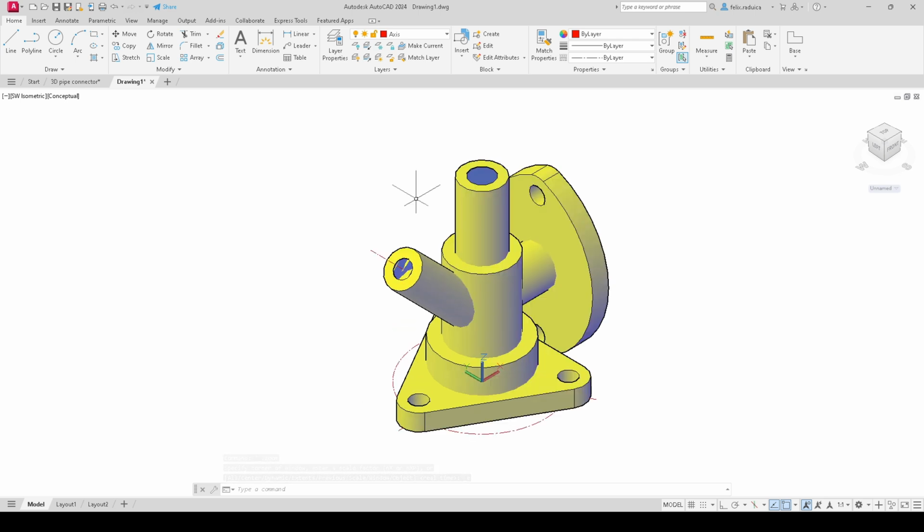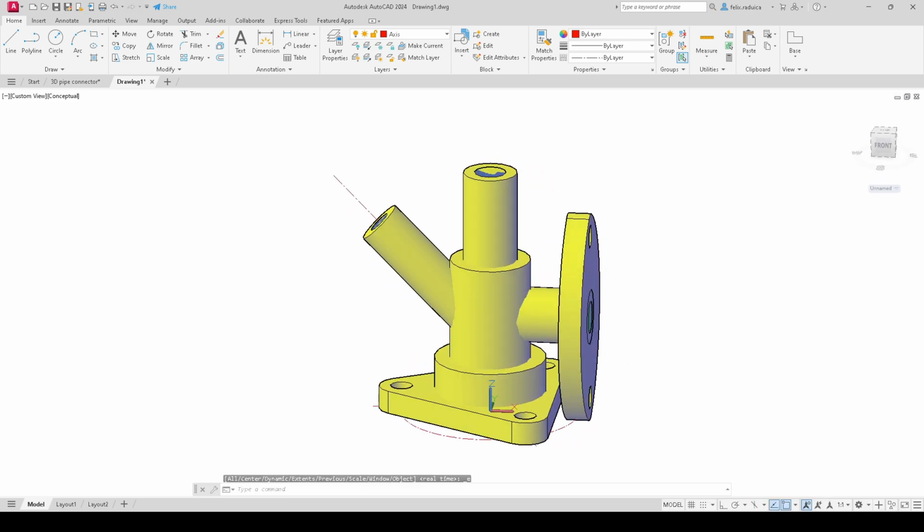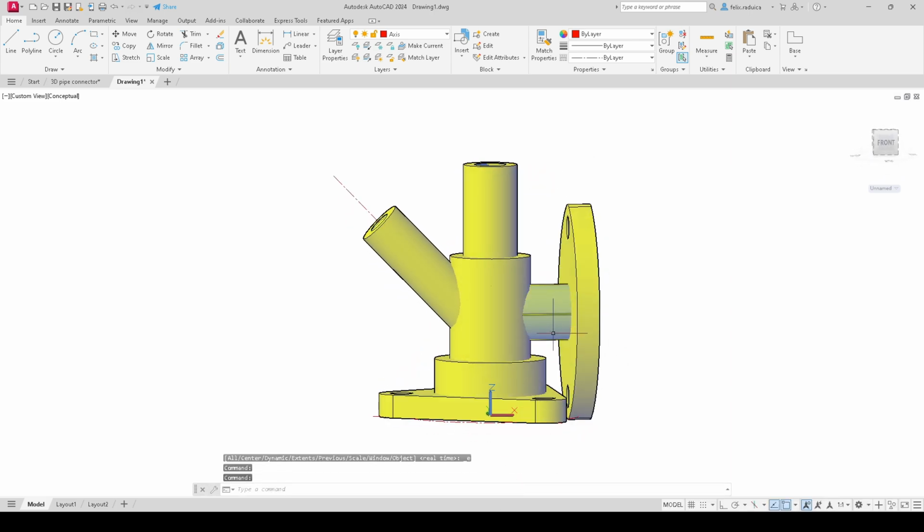At this point, we are about to perform the final operation between the outside geometry and the inside geometry, and it's a good time to think about if the model is okay or if we have done some mistakes. And in this case, I realized that the flange here is not properly generated. So I'll show you another way to model the flange in place.